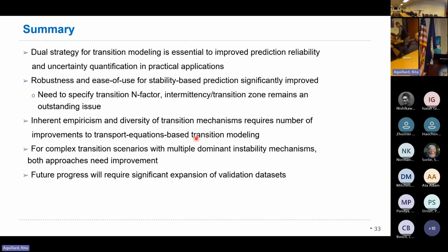So how does the total cost compare to a fully turbulent simulation? Compared to a fully turbulent computation, say if you take a PDE-based method, it depends on which transition model you pick. Most of these, except for the gamma, add 2 additional equations. So you have to add that into the cost. 20% cost.